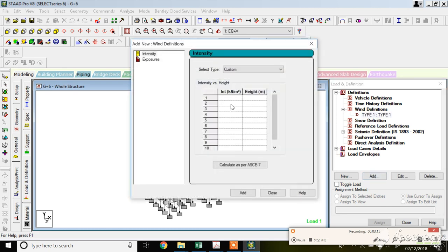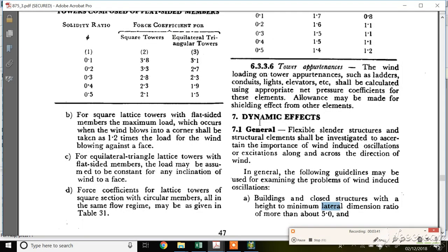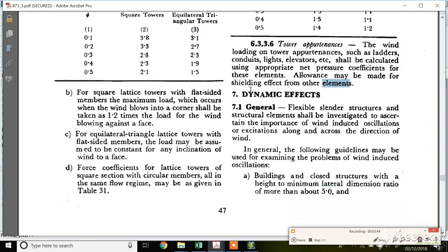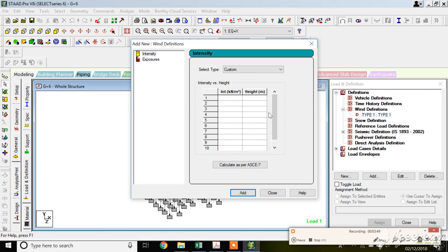For this lecture, I'll just give you a brief idea of how wind load is applied. We calculate wind pressure as per your internal pressure coefficient, external coefficients, and gust factors as per your height, working with factors, coefficients, your K1, K2 and K3 factors as per IS 875 part 3, which is for your wind loading, where the dynamic effects are considered. After considering all these factors, I'll come up with wind loading in a different set of videos, with more calculations. I'll just show you an example.